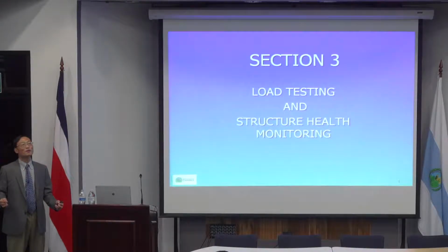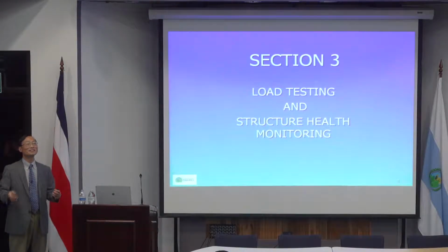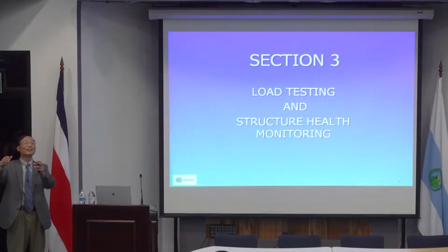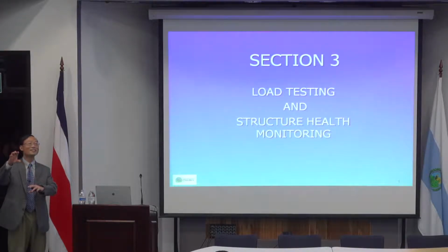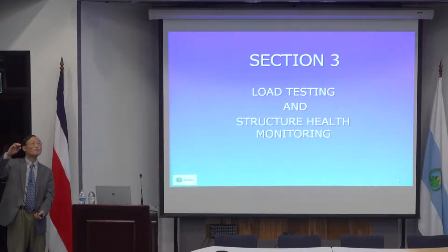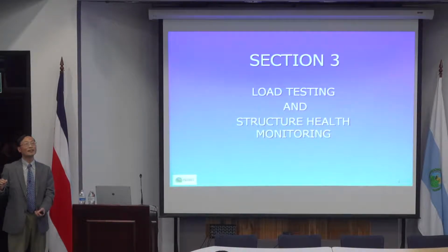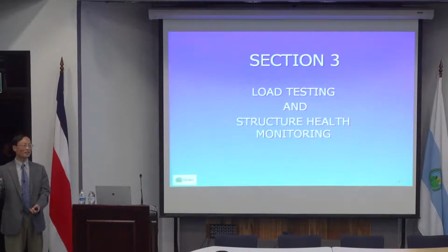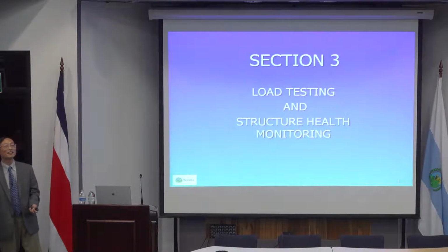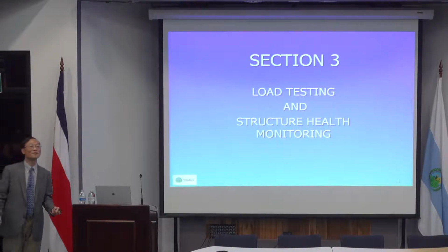So for non-composite, typically when you do the finite element model, you just use a net section. And if you want, you can add a deck section, but if you add these two pieces together, it's very small. But if we assume it's composite, then the section modulus is much larger. So that's why when you do a regular calculation, you assume it's non-composite.